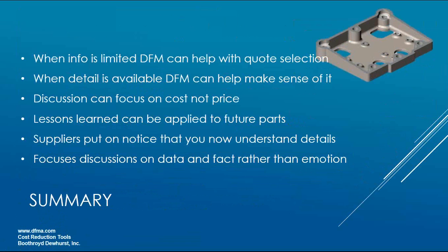And that is that if you take the result of a DFM analysis piece cost and you divide it by 0.8, that should get you to something close to what a supplier quote is. I can never remember the third grade math on it, but that's somehow different than multiplying it by 1.2, I think. Anyway, it's assuming effectively a 20%, and I'm not going to call it profit. It's SG&A, transportation, whatever else you want to throw into that bucket.